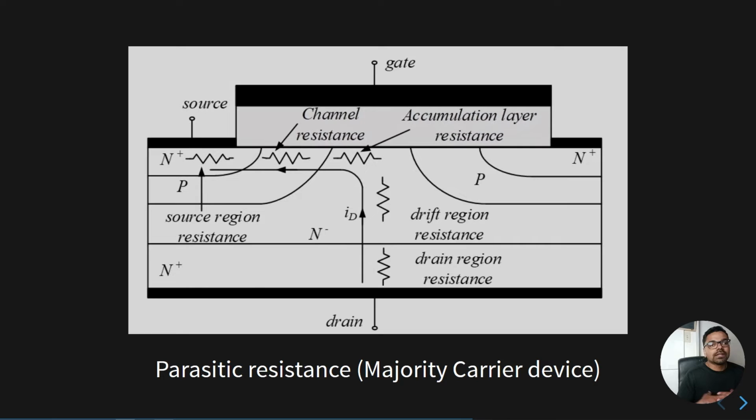First and foremost, it has high switching capacity. You can switch very quickly, but it also has a resistance. That's the reason why a MOSFET is used for brushless DC motors, but you want to take care of the resistive nature when it's conducting. All of these parameters are important when you look at the data sheet. You also want to know how much heat is dissipating from your MOSFET. This is the kind of information that is relevant when selecting a MOSFET. So you always want to know the turn on voltage and what resistance is there when your MOSFET is on. This is what the parasitic resistance is. It shouldn't be there, but it's there.